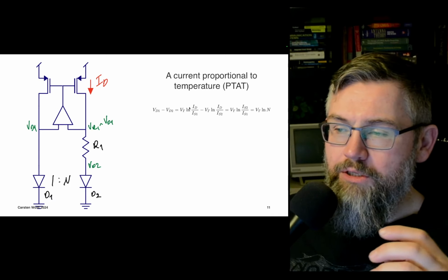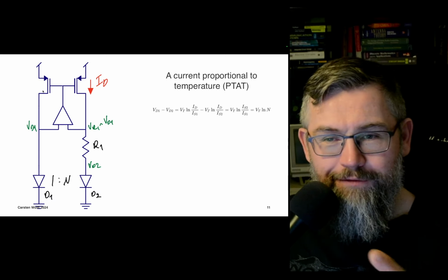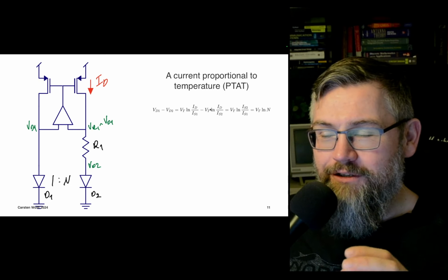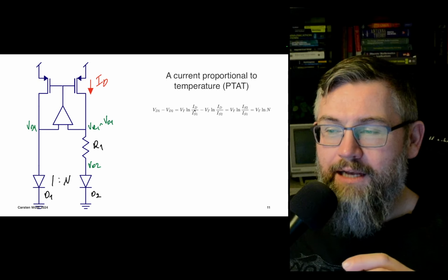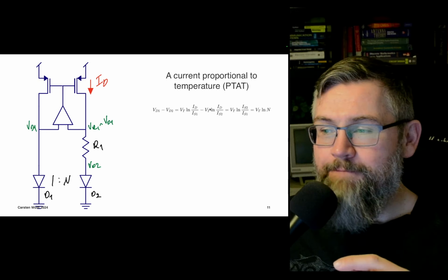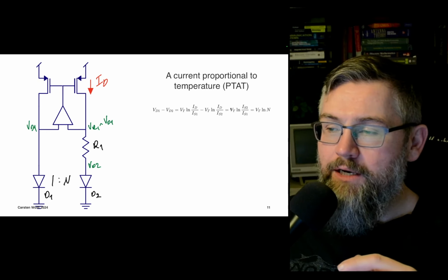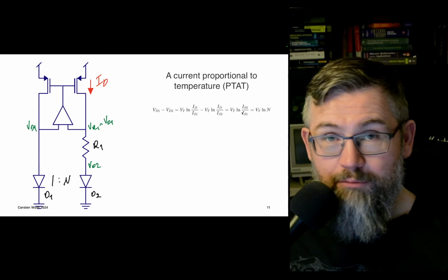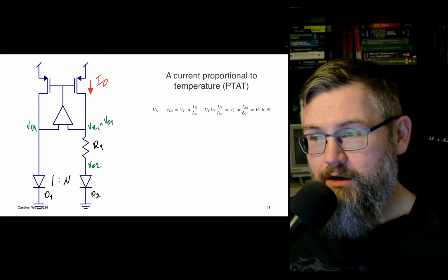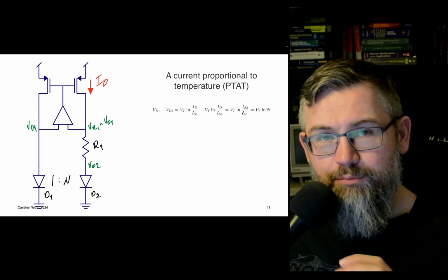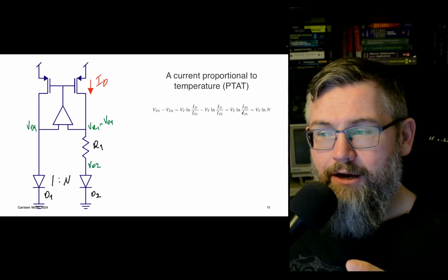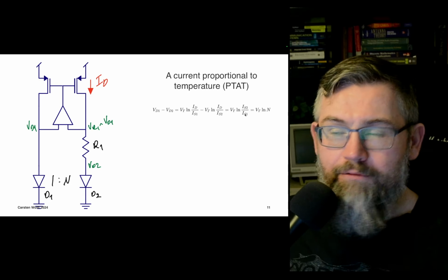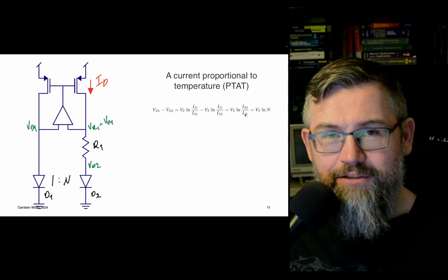And now, we know that if the current mirror is matched exactly, then the currents in the two are the same, and the ln of ID disappears. We're left with a relationship between the two scale currents. Now, as I said, if we have the same orientation and the same doping, then the only difference between these two diodes is the area. And now we can just plug in the scale current. We can take it out, so everything but the size difference disappears.